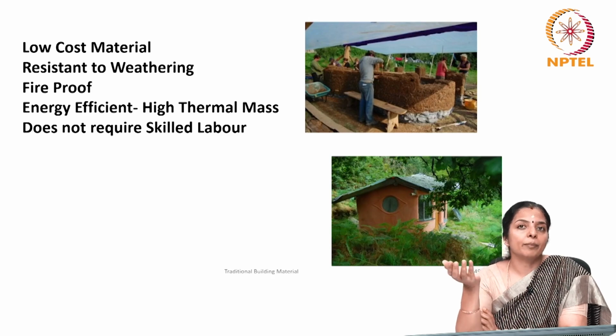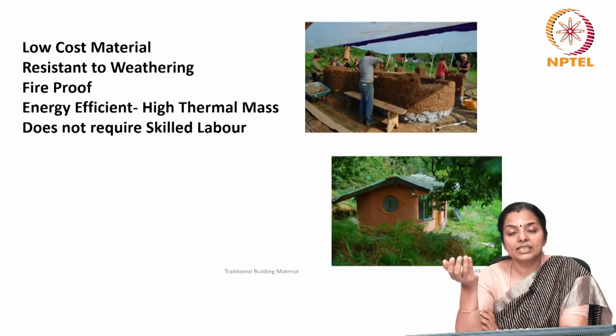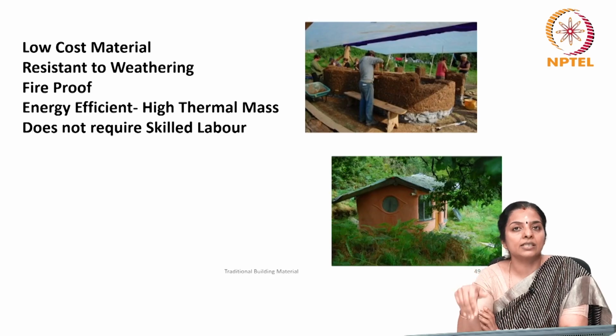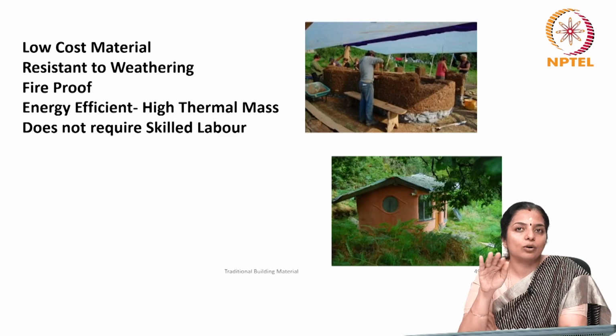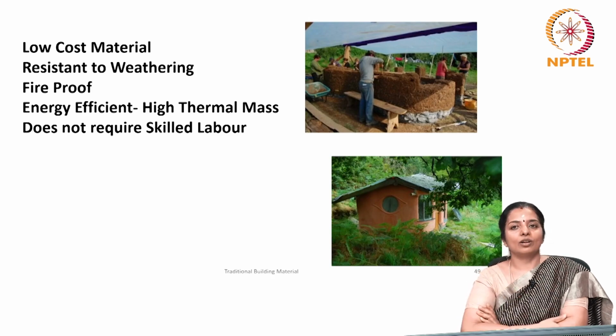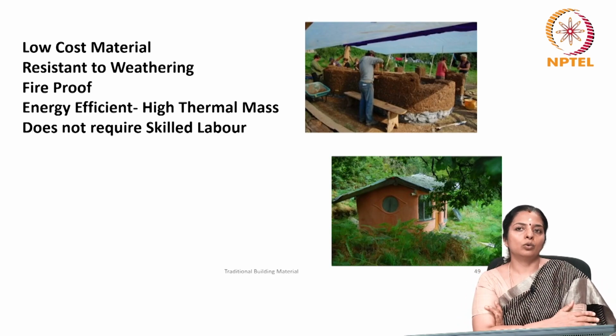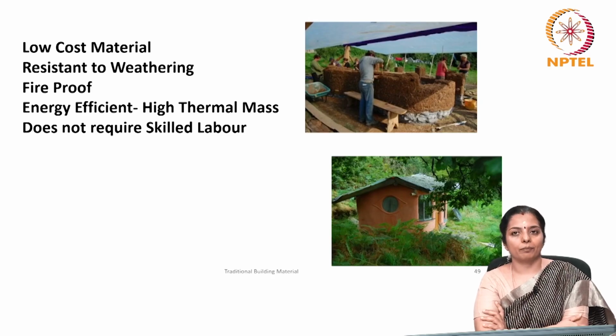And also you should remember, every cob wall building must have roofs with long eaves, as shown in the picture. So it should not be like a cob wall with a flat roof or something like that. The eaves must be very long. That is also called the boot and hat method. So this uses a very impermeable foundation, which we call the boot, and wide roof eaves which will shield the walls and protect the walls, and it's a good way to prevent excessive exposure.